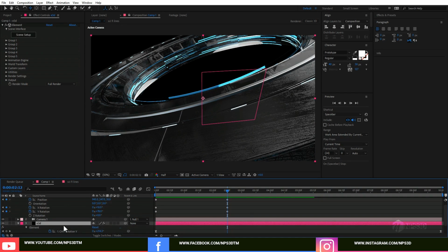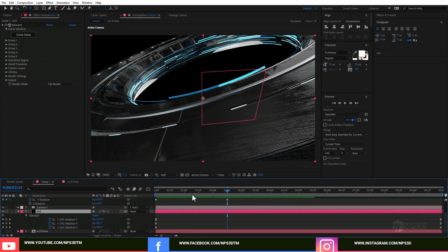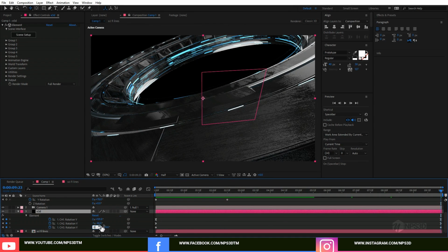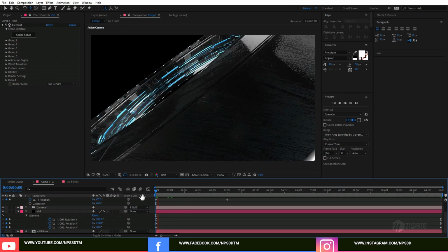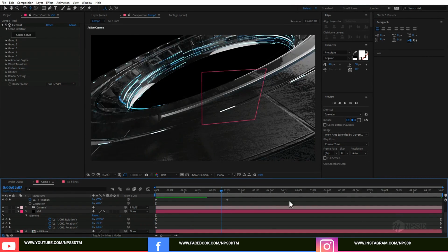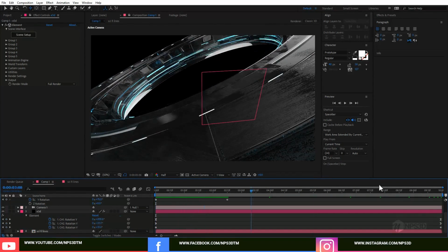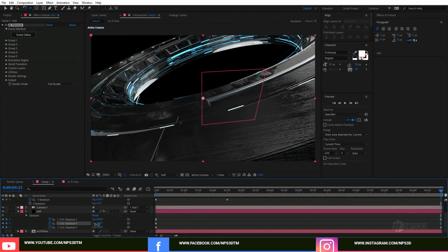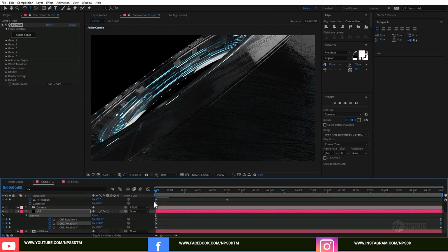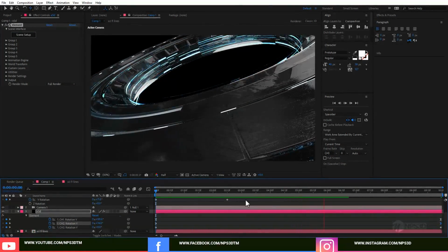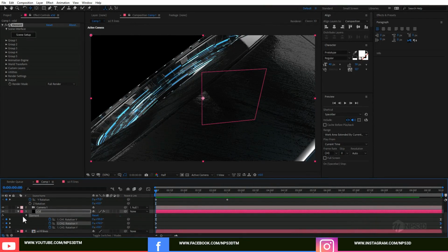So go to the Element 3D, press U and go to channel number 3 and make them slower. So come over here and make it 0 and here make it 180, or even make it slower, so make it 90. Right, and for the other two also. So I'm going to bring it down. Right, now it looks good to me actually.